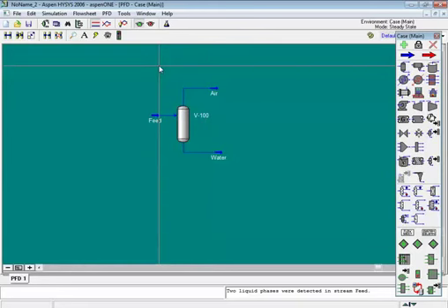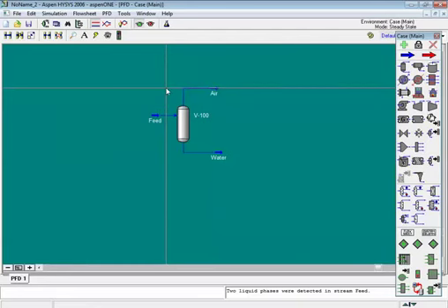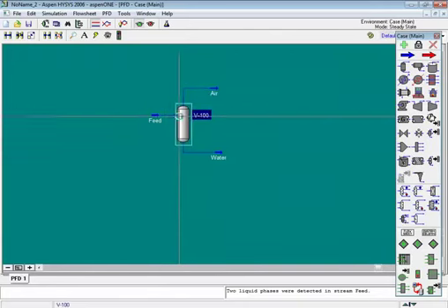It means the flow should go from higher pressure to lower pressure. That is the pressure flow equation that needs to be understood. In steady state simulation, you do not care about the pressure flow. Even if the pressure is higher downstream, it will still show a flow towards the higher pressure, which is not practically possible.